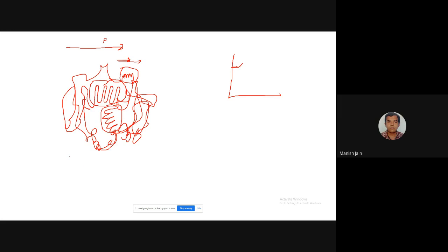then due to the differential force of each layer, the entanglement starts to open. Because these are a bunch of molecular ribbons, like noodles, a bunch of noodles. When you force the noodles with very high shear rate, the entanglement between the noodles starts to be removed. So once the entanglement starts to be removed, the viscosity will reduce because the resistance will reduce. Then the viscosity will reduce.